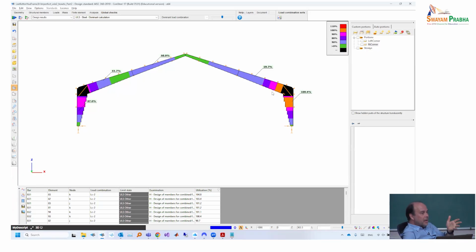Okay, obviously, even if we have a continuous connection between column and web, it's not a fixed end from the LTB point of view, because it's the poor column by torsion that would need to provide the fixity, and its torsion resistance is close to zero, but it's not zero, and that's a huge difference if something is really zero or just small. And many, many small things together are producing a visible something.